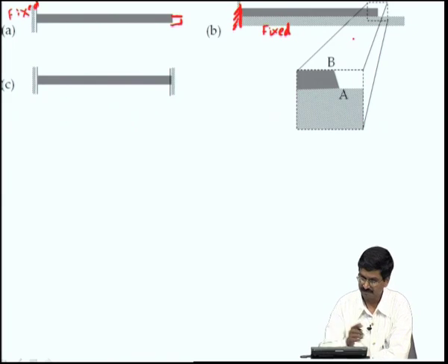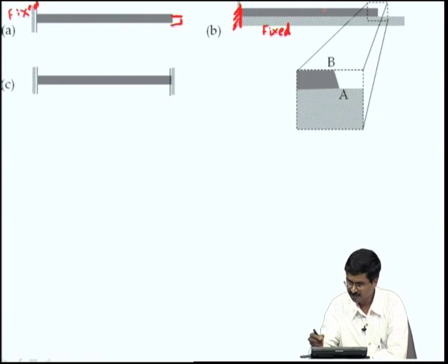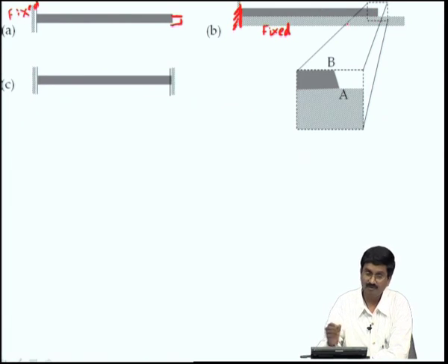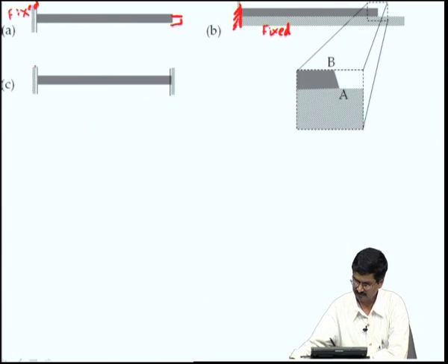When that happens, let us say this material has developed a tensile residual stress. That means that to counter that, it has to contract and create a compressive stress, cancel it and become stress free. If you look at this portion, the bottom one cannot contract, because it is fixed to the substrate, whereas the top one can. Let me mark this with the mouse.